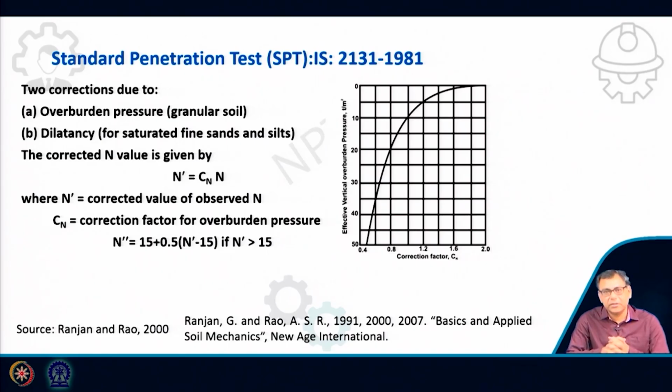So here pore pressure will get enough time to dissipate, and negative pore pressure will not generate. That's why the strength will also not increase, and that's why in the real foundation this higher N value will not occur. So we have to apply this correction to reduce that N value, which will give you the N value as expected.